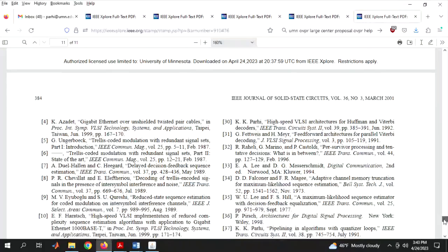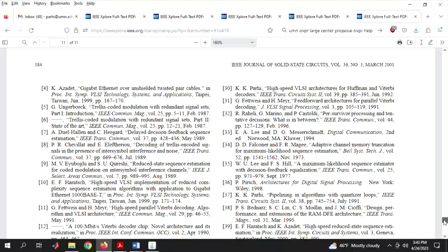the 125 megabaud rate. So that's the 1991 paper that they are using to speed up the receiver design of the gigabit Ethernet. It is true that the simple IIR filter pipelining itself may not have much practical impact, but the idea that came out of that has had tremendous impact, whether in simple Ethernet or 10 gigabit Ethernet, or in other backplanes and serializers, deserializers.